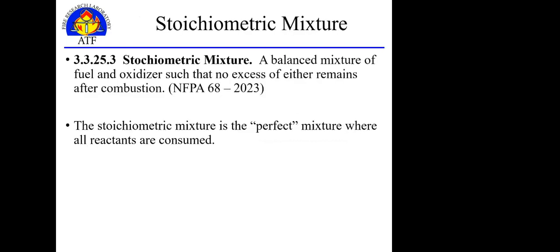So just kind of reiterating, the NFPA 68, which is a guide on explosion venting and reducing or preventing damage, defines that stoichiometric mixture as a balanced mixture where ultimately we have no fuel or oxygen or oxidizer left after that combustion reaction. So all the reactants are consumed. It's that perfect mixture that we're shooting for.